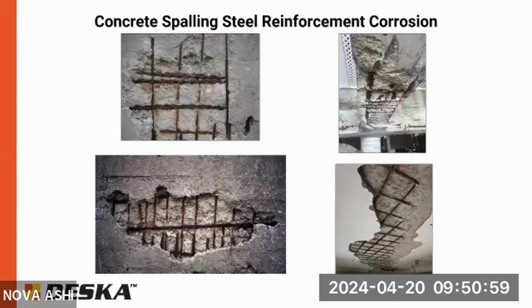But in this case, it's steel reinforcement inside of concrete, and the force is powerful enough that as that steel expands, it spalls the concrete. Usually it starts by delamination. If you tap on it with your flashlight or a hammer, it'll sound hollow. And if you don't do anything about it, you keep letting it corrode longer and longer, eventually the concrete will fall off. If you drive underneath a lot of bridges, you'll probably see something like this.